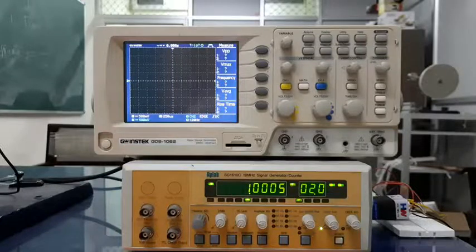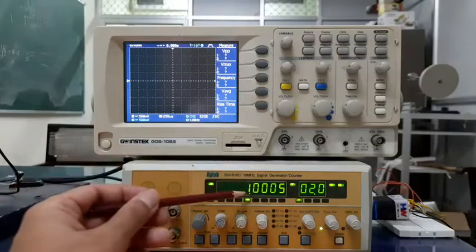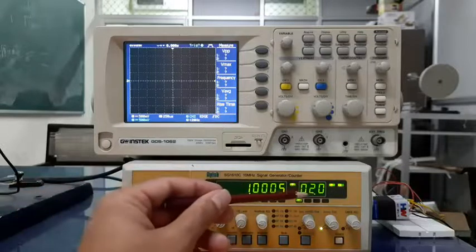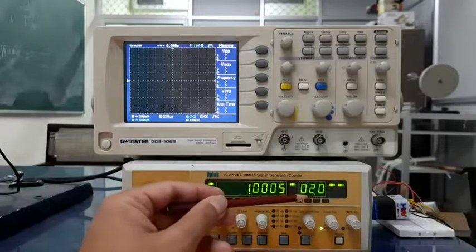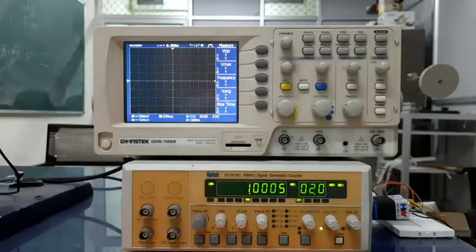Here I am going to use a reference signal to show you how to set the oscilloscope properly, and that reference signal will be taken from this function generator. So I have a 1 kilohertz sinusoidal waveform with an amplitude of 2 volts peak to peak, that means plus minus 1 volt, right? That's the output of the function generator, which I now want to feed into the oscilloscope and see how a 1 kilohertz sinusoidal waveform with 2 volts peak to peak amplitude looks like.